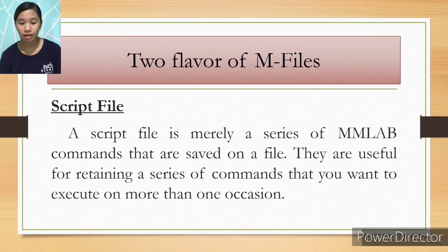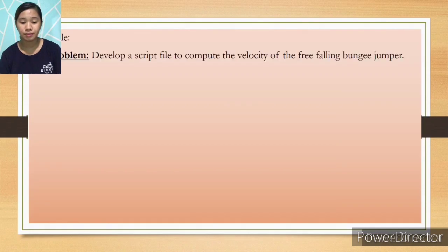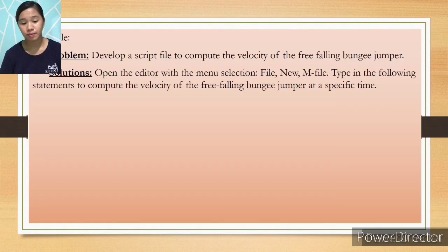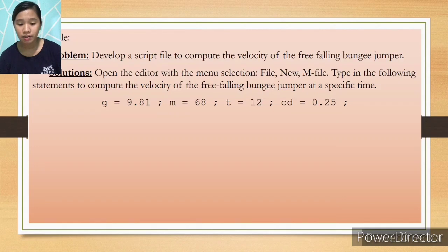Example of a script file. We have a problem: develop a script file to compute the velocity of the free-falling bungee jumper. The solution: open the editor with the menu selection File, New, and File. Type in the following statements to compute the velocity of the free-falling bungee jumper at a specific time. g = 9.81, which is the gravity.